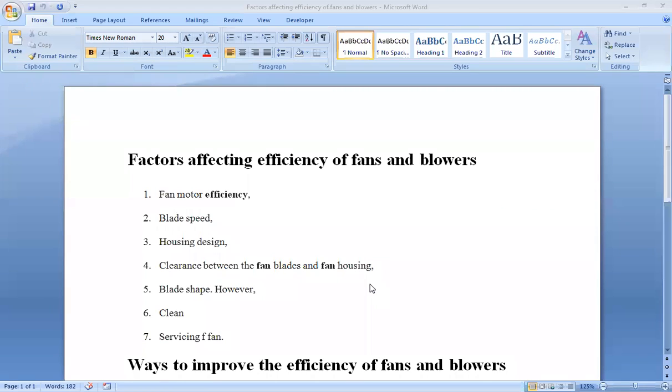A lot of dust and dirt particles accumulate on the fans. There is an accumulation of dust and dirt particles on the bearing section where the fan rotates, and there is an obstruction to the rotation of the fan. The fan is not able to rotate precisely, accurately or easily, so we have to clean the bearing and the fan blades, so that it will blow the air easily.